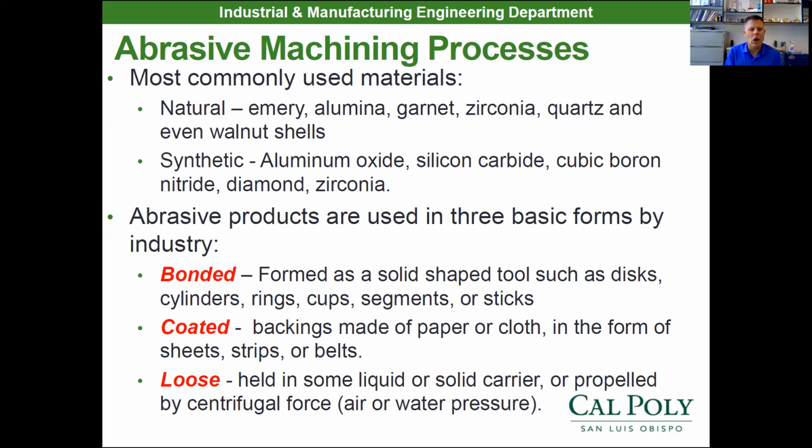And we'll end up using coated abrasives and bonded abrasives when we start making air motor parts in the lab during week 6. In fact, we'll have a bonded wheel when we cylindrical grind or centerless grind the pistons. And then we'll have a belt with abrasives coated on it to chamfer the tool steel main shafts when we get to that point. So we're going to use bonded and coated abrasives quite a bit over the next couple of weeks in the lab.